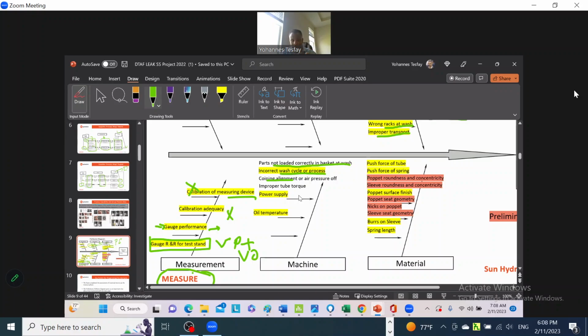So to make it very smooth, they put the ball and press it with pressure. When the ball is pressed by pressure, it deforms the surface. So that makes the part good.